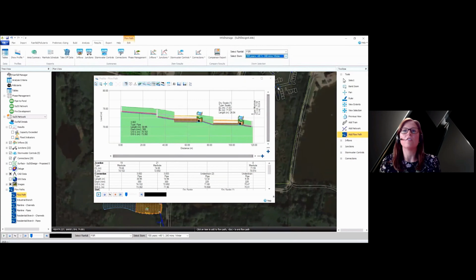InfoDrainage can offer accurate graphical representation, but also hydraulic representation, ensuring that the water passes through these green infrastructure systems central to the hydraulic engine, as well as giving consideration for those different levels of filter media, exactly how much there is, the porosity, and the effects those structures have on slowing down the flow.